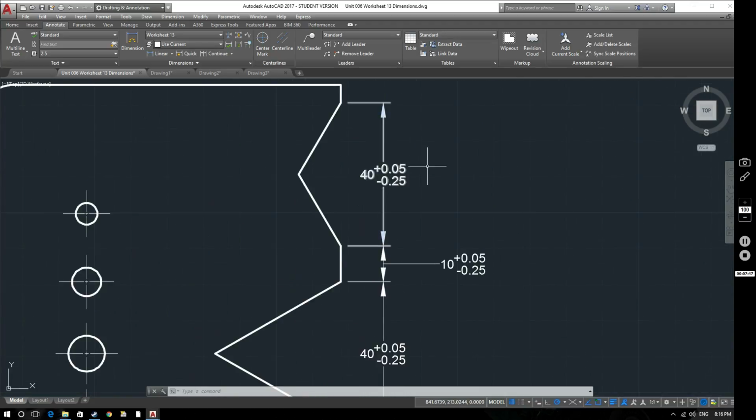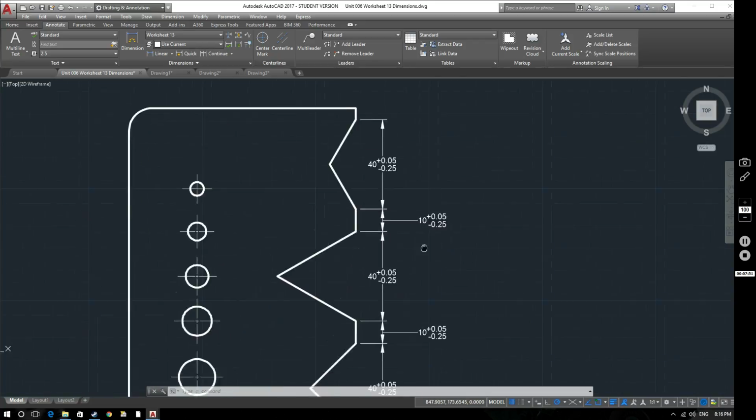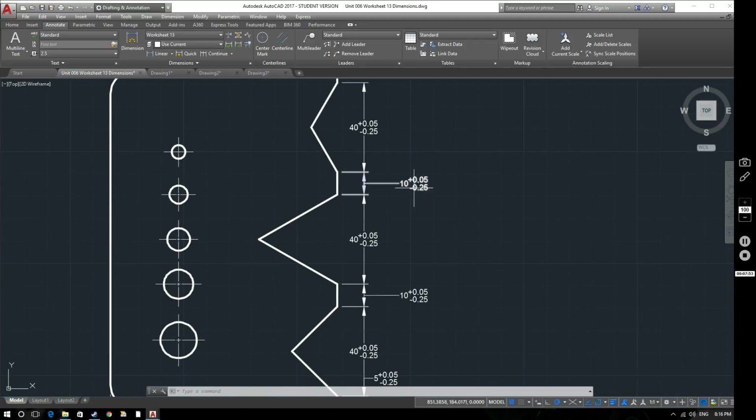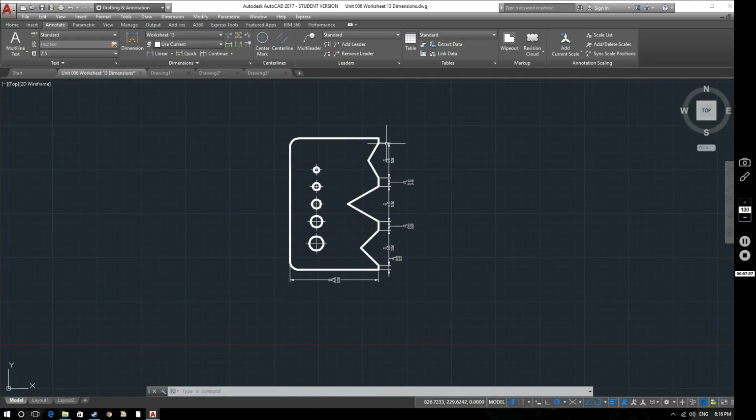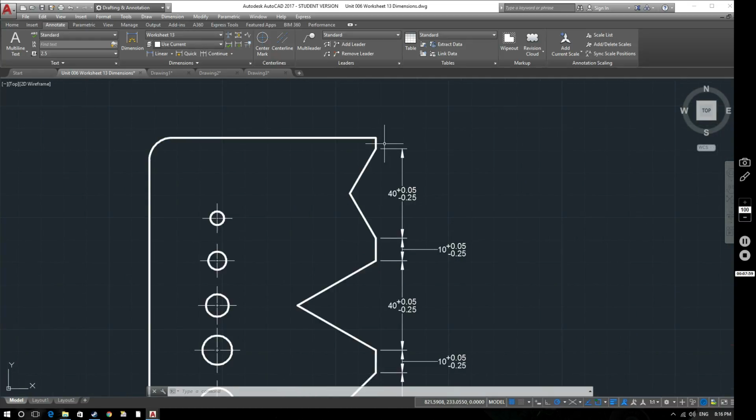However, what you've got to take into account are these tolerances. If on every dimension 0.05mm is added onto each length, then by the time we get to the overall length of this, this is going to be more than 150mm. Similarly, if we put less than it, then the overall length will become less than 150mm.